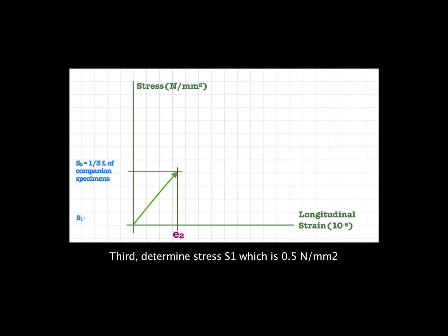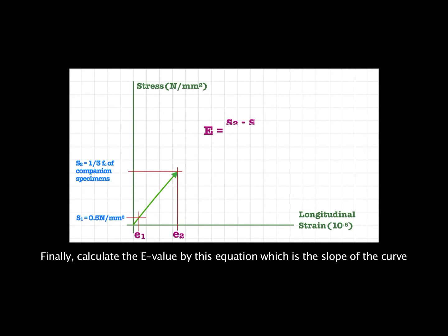Third, determine stress S1, which is 0.5 Newton per mm square, corresponding to the longitudinal strain E1. Finally, calculate the E value by this equation, which is the slope of the curve.